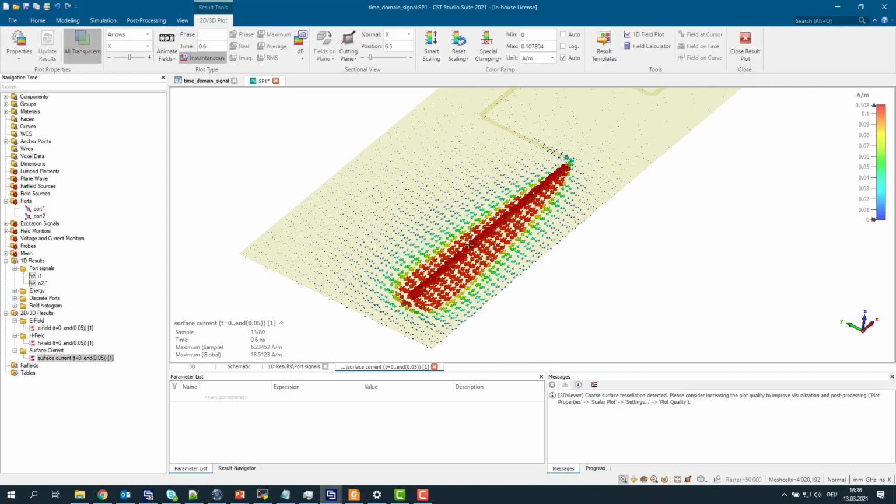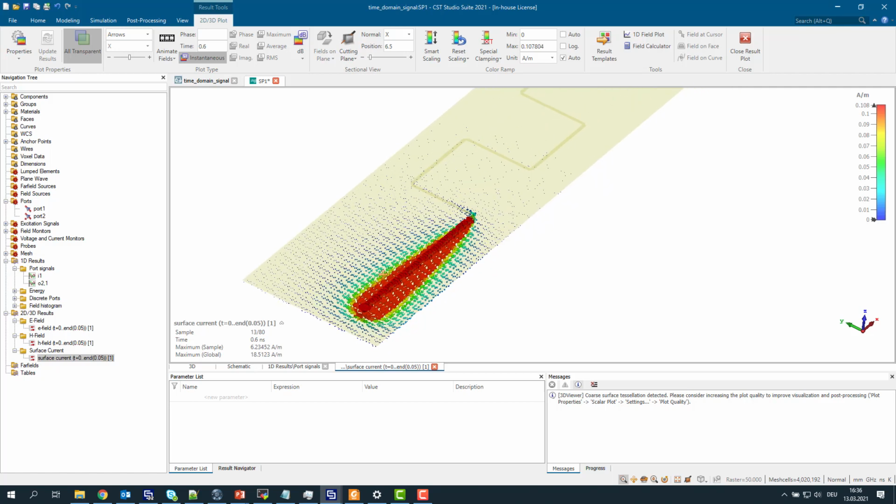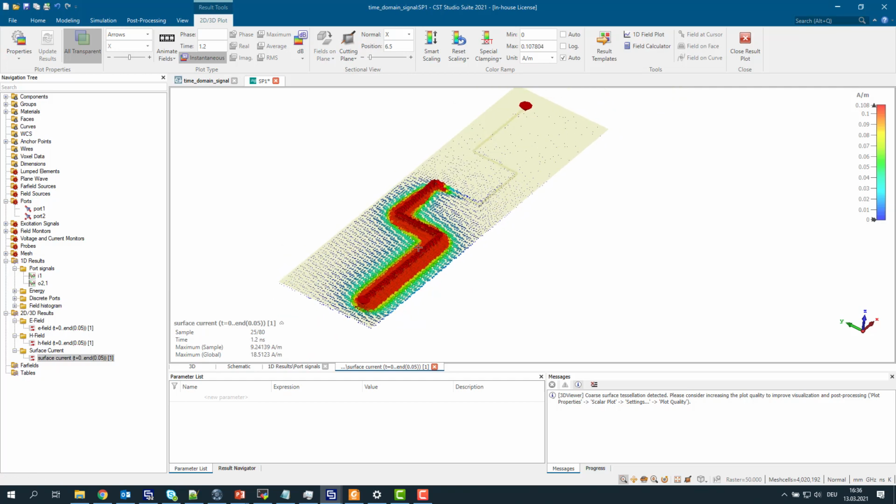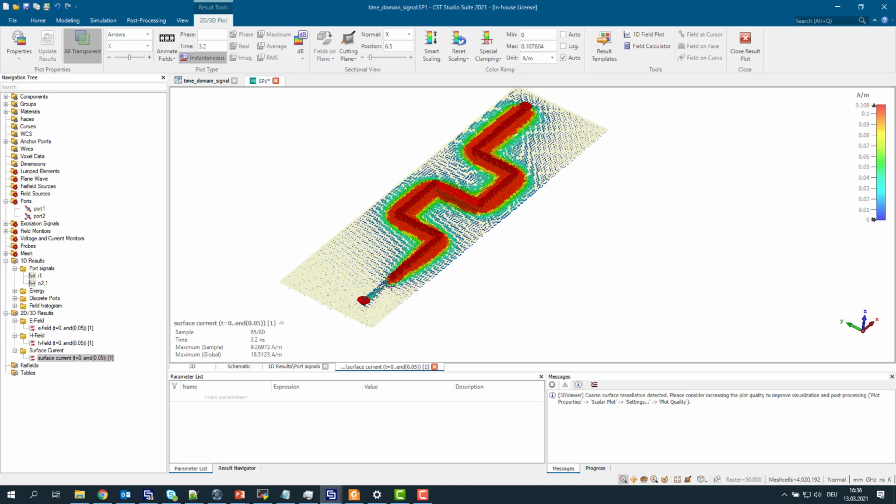There is, I think, a very important step in trying to understand signal propagation: also thinking in terms of electromagnetic fields. So we can now let the current propagate. You can see this is our pulse. The signal trace is pretty long, so when it arrives here at the point 2.5, it's basically the end of the signal, and you can see also now the end of the signal. That's really a true time domain description of the signal propagation, and we get some really interesting fields.